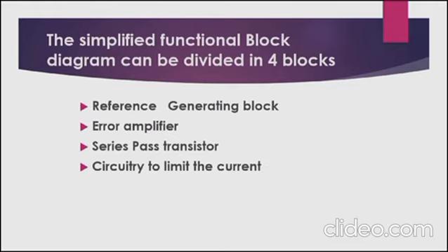Second, the error amplifier. Error amplifier is a high gain differential amplifier with two inputs, inverting and non-inverting. The non-inverting terminal is connected to the internally generated reference voltage. The inverting terminal is connected to the fed back regulated output voltage.